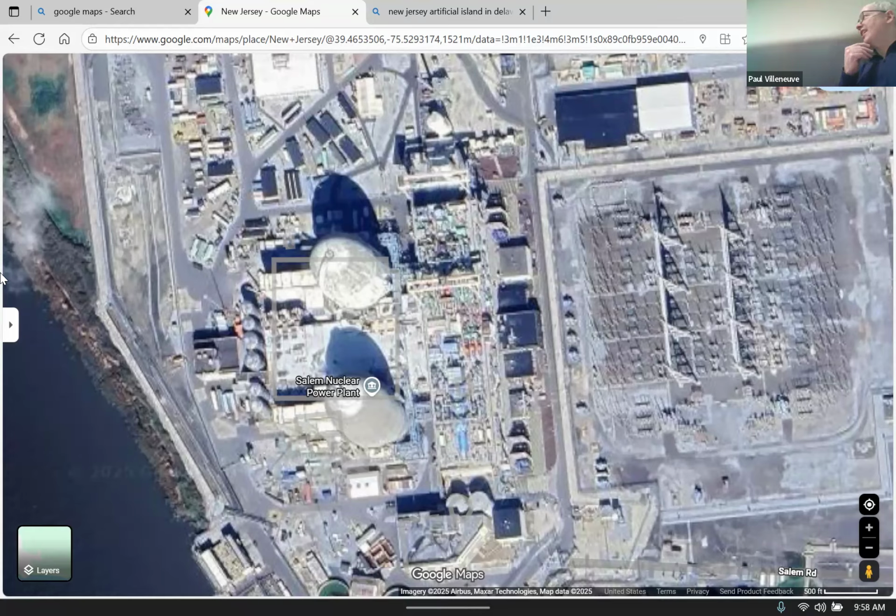And one of the things they did is they had these control systems for these moisture separated reheaters, which is, if you've taken MET433, you learn about power cycles and steam cycles. And this type of steam that you find in a nuclear power plant tends to be saturated steam. It tends to be lower quality steam. And so these moisture separated reheaters are unique. You usually don't have to separate moisture in the steam. But in these, because they run at such a low temperature based on the pressure they're at, they actually need to do it.